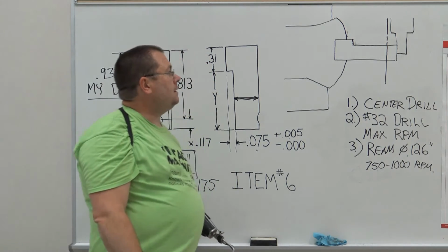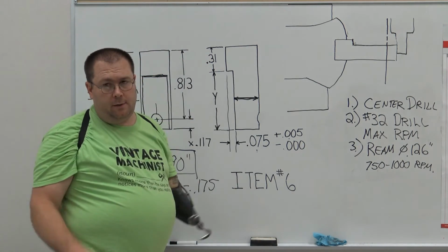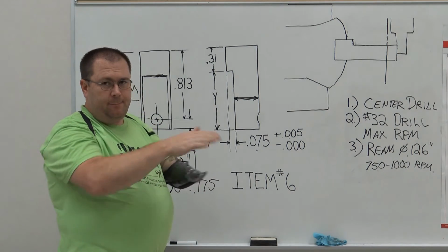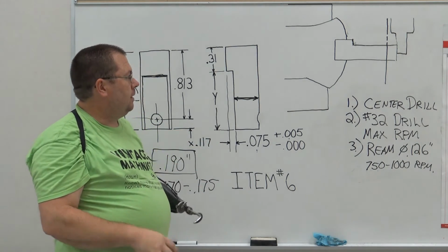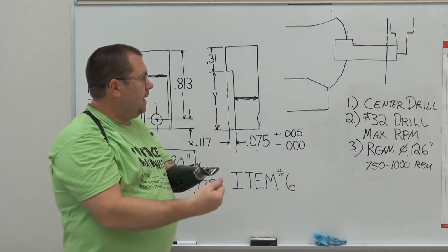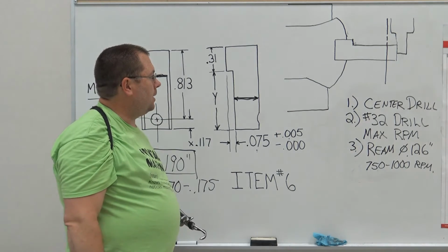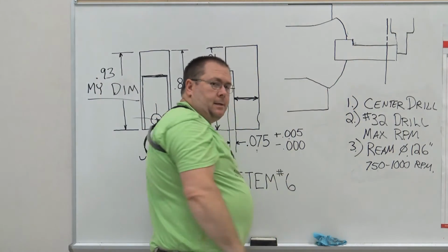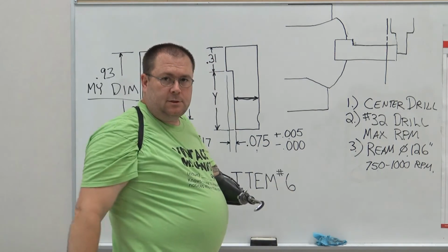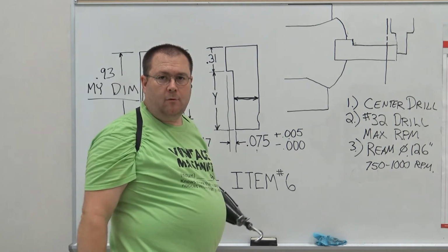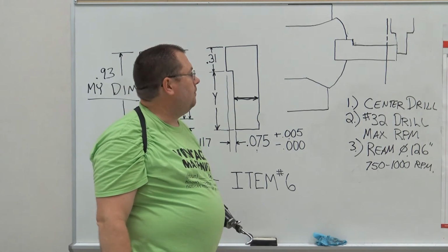As long as it rotates fine, go ahead and take your crankshaft out, put it back in your toolbox. While this part is in the vise and in your collet block, go ahead and deburr it with a file, emery paper, countersink for the hole, both sides, top and bottom. Okay? I'm going to take some emery cloth up around the top of the piston where I put that little step on there. I'd like it to be deburred so you're ready to rock and roll when you go to put the thing together. Okay?